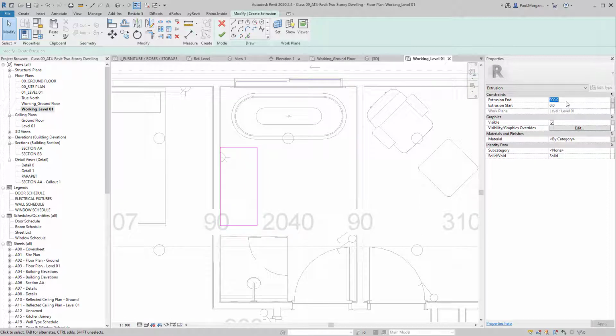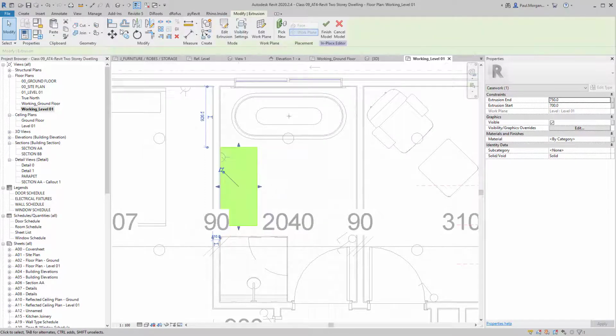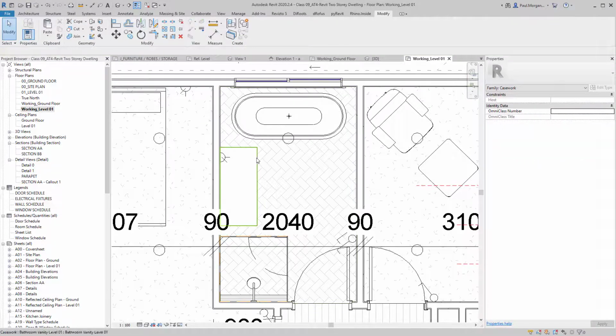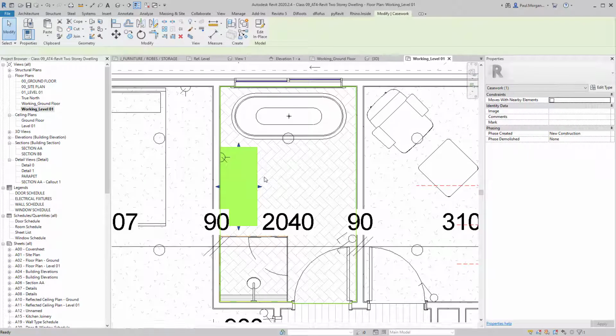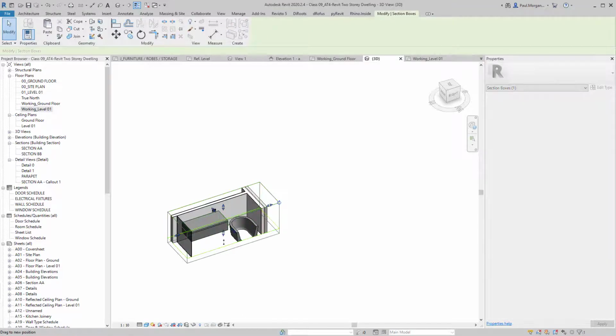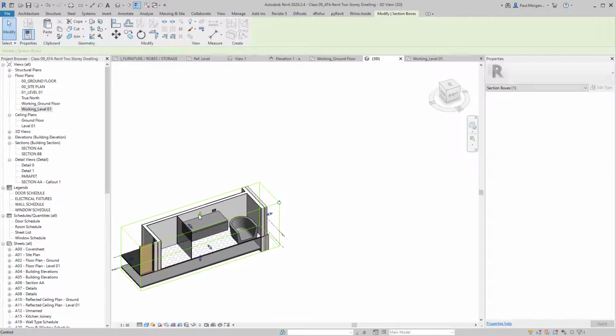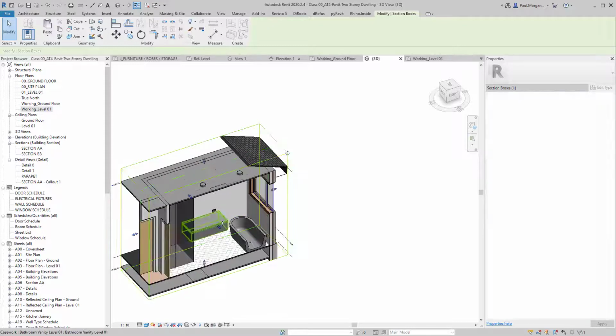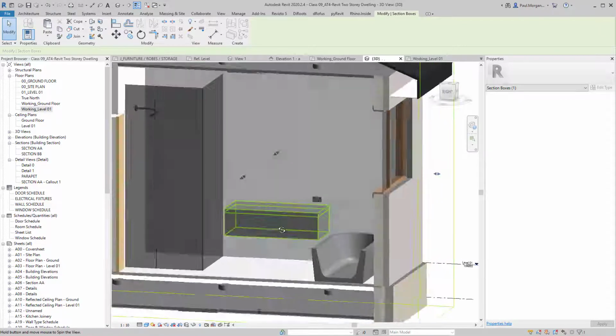And then again, the same deal with sizes. So it starts at 750, so it ends at 750, but the first layer starts at 700. So that's our bench top. We can say okay, and then I can just copy that, Control C, paste in the same place, and just edit the second one. So the second one ends at 700 but begins at 400, like so. Say okay, and let's just make a section box around this. Okay, so you can see how that's coming together.